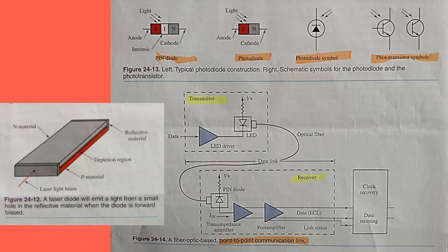Fiber optic transmitters. Fiber optic transmitters are usually LEDs or laser diodes. These diodes produce the beam of light that carries the signal. Many various electronic systems are used to convert the electrical signal that drives the LED or laser diode. The light signal can be either amplitude modulated, AM, or pulse modulated, PM. Frequency modulation, FM, does not work well with fiber optics, and it is still being refined. At present, most signals are either AM or digital.